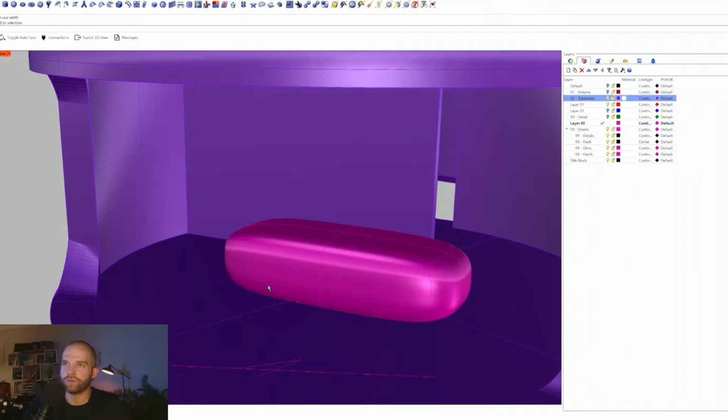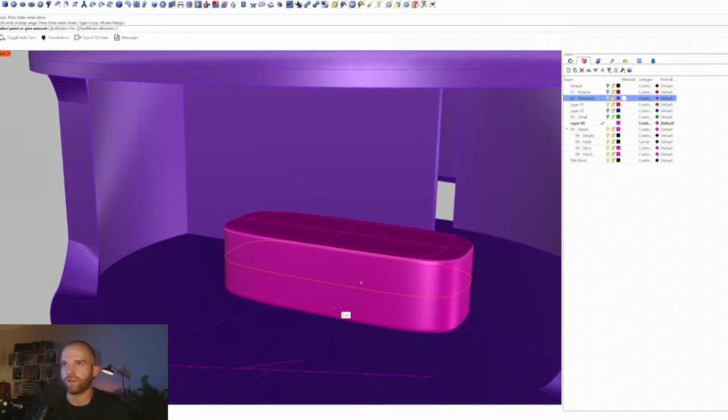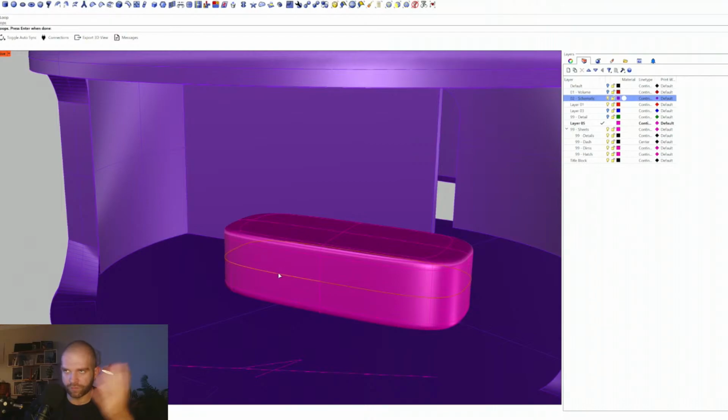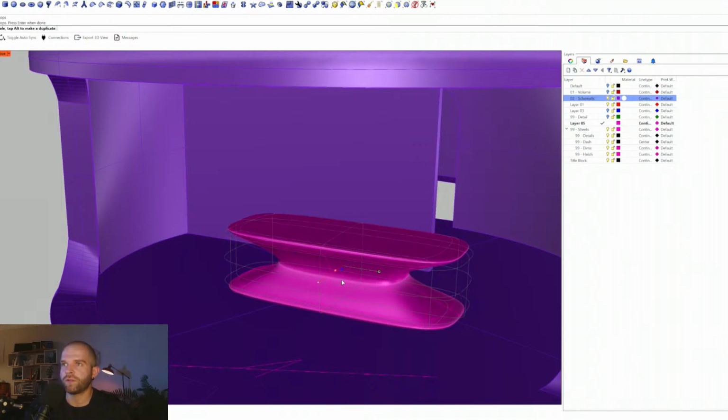And so what we want to do is insert an edge loop. Insert edge. Select this middle one. Do both sides. And then we can approach that towards their tops so we can get that harder edge. And come on, trying to snap it. There we go. Now we'll select this inner, or the middle loop, and I'm going to scale that in a whole ton. Bam! Futuristic, sci-fi, cool.